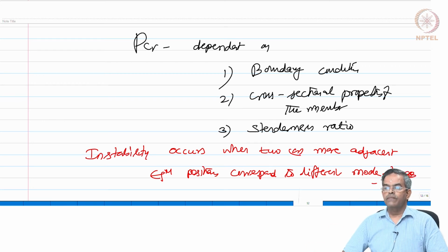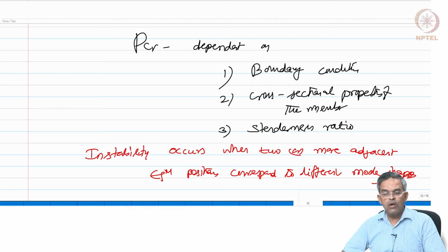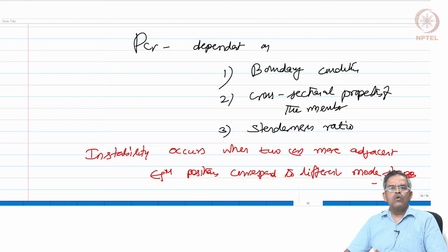That is why, friends, you note in well designed structural systems there exist distinctly different well separated mode shapes. On the other hand, the frequencies of the system will not be closer, they will be well separated. So, the mode shapes do not overlap very closely with each other, because if they have very closely related condition, there can be an overlap and that can cause instability.